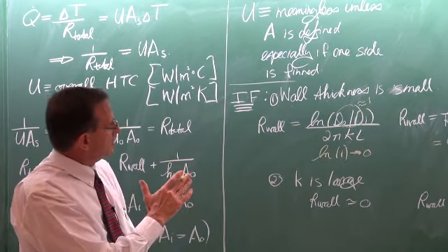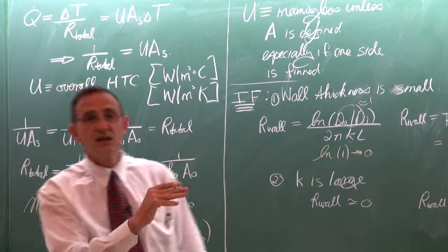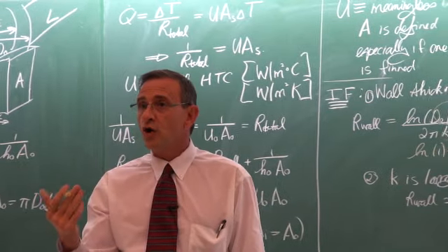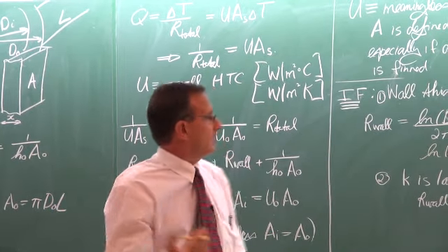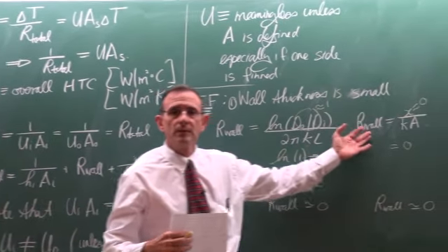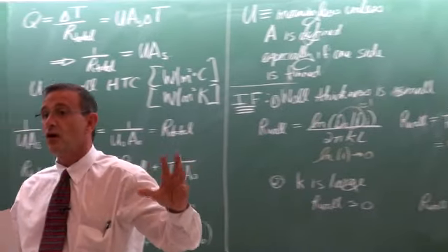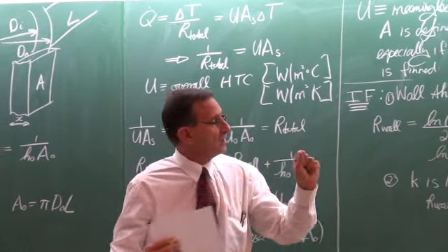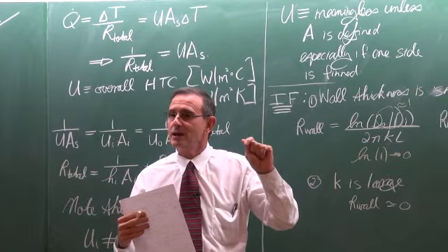It's very interesting that with many heat exchangers these days you actually get plastic heat exchangers in the radiators of cars. Okay. And again, if you would now look at the resistance of the wall, plastic does not have a high thermal conductivity. But the plastic walls can be made very, very thin.